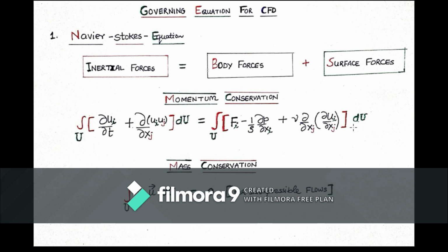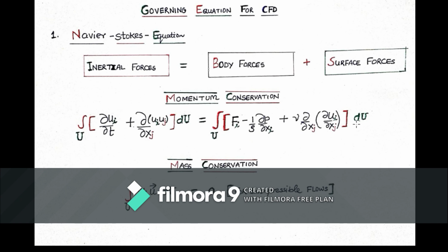But here I would like to point your attention to three terms: pressure, shear forces, and the convection term. For these terms, is there a meaning for taking a volume integral? I don't think so, because pressure acts on a surface, shear forces as well act on a surface. The convection term also is a surface phenomenon. So how can we take a volume integral for these terms, or how do we go to the next step?